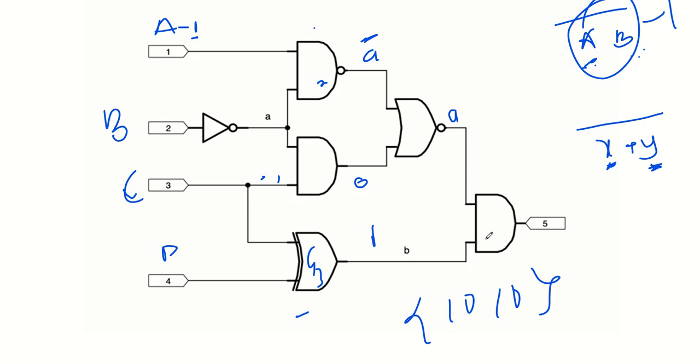In an AND gate, to ensure that this gate allows only A to propagate, or A determines the output, we have to set here to 1. And when we set here to 1, then A will come to the output. Now, to determine what the exact inputs were, we have to propagate backwards. In propagating backwards, we realize that this circuit here is supposed to output 0.